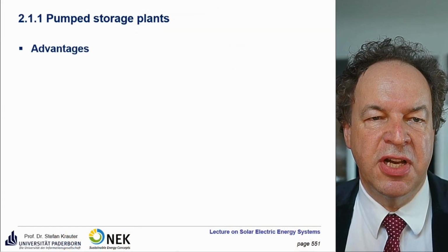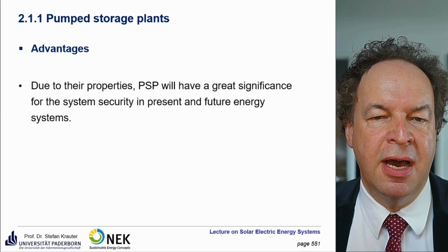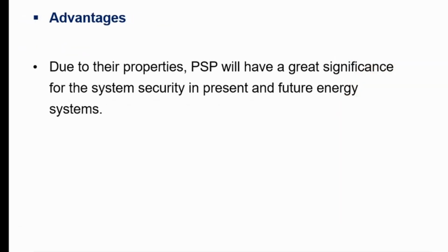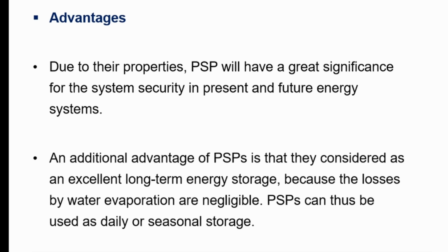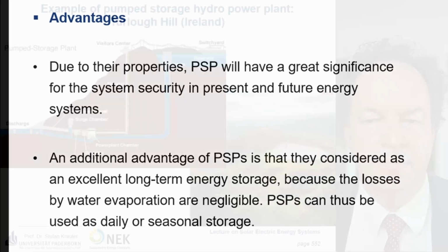So advantages of such pumped storage power plants are they provide system security presently, but even more important for future energy systems. They are also considered as a long-term energy storage because the losses by water evaporation are quite negligible. So this can be even used for seasonal storage, not only for daily or weekly storage.